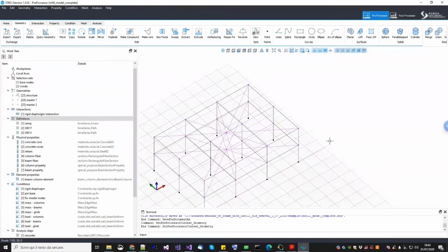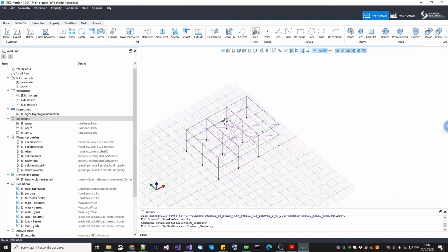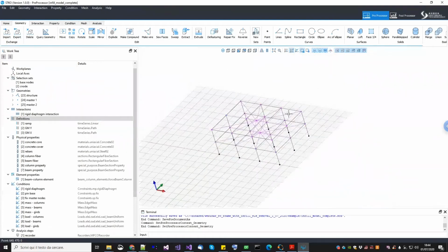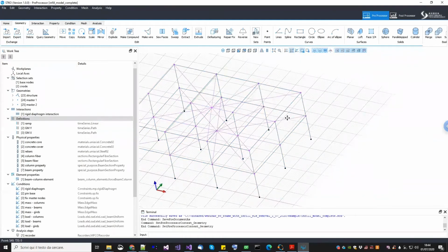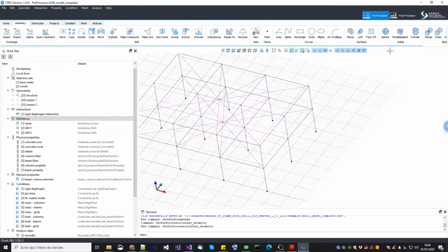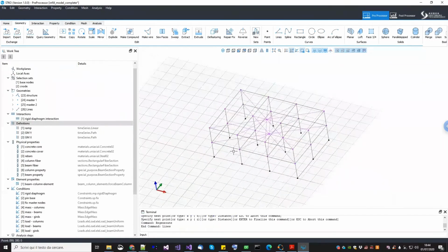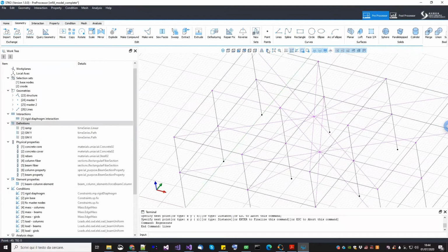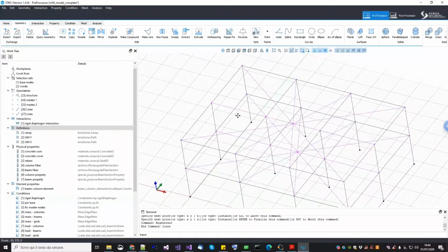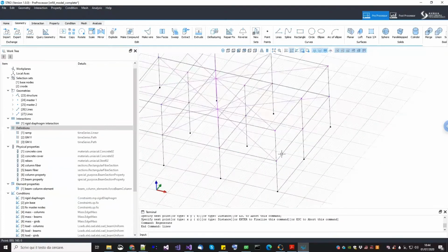So the first thing that you have to do is to prepare the geometric model. As I said, inside STKO, this model will be assigned to a surface element. So how do I fill these holes with faces? The first thing that you have to do is to create a construction line down here so that we close these holes. And then we do the same on this other side. So, bottom to bottom point. I did it because I need to close this area.